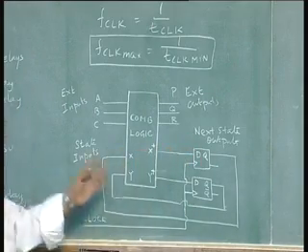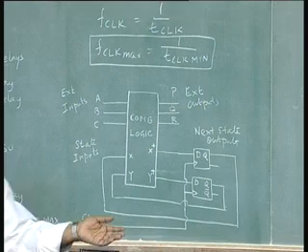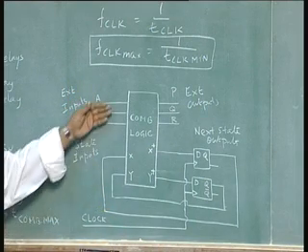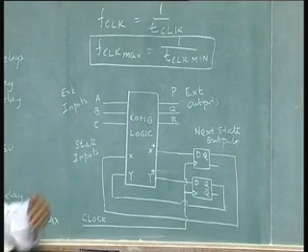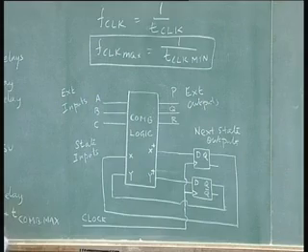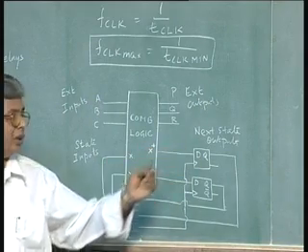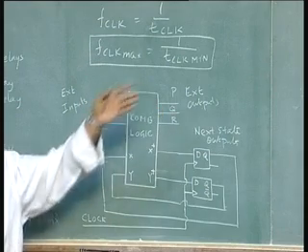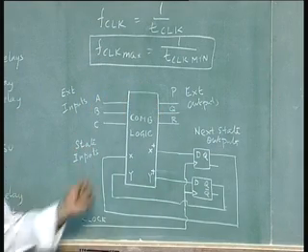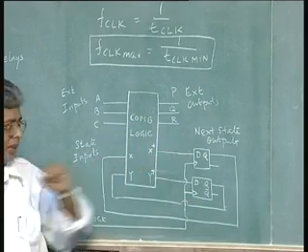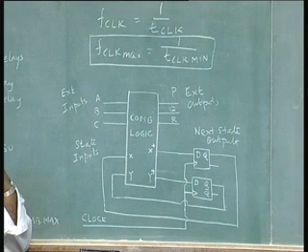That is why now this whole thing becomes a sequential circuit, which has some practical meaning, with a b c as the inputs. Maybe in a traffic light controller situation, this can be the different sensors or timing elements, and it could be the state in which the circuit passes through, and this can be different lights, red, green, yellow lights which are required in the traffic intersection. So, this is how you have a normal sequential circuit or any standard digital system configured or defined.